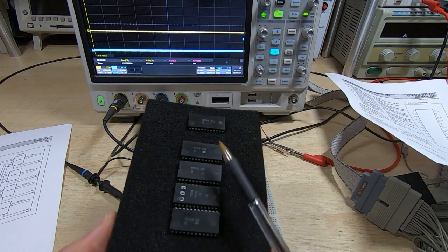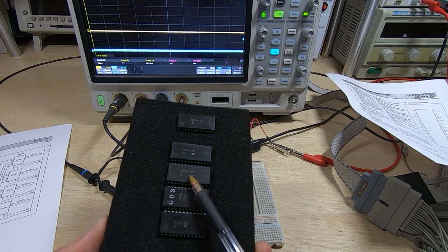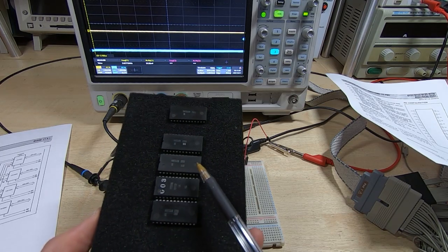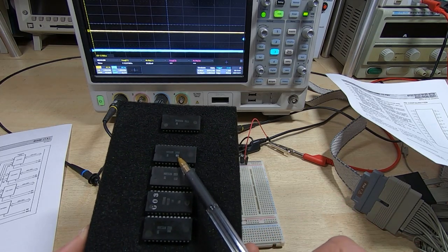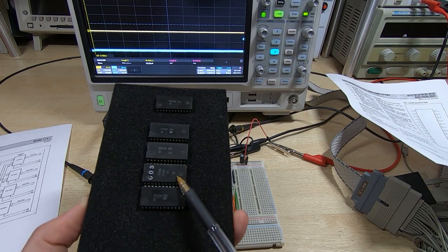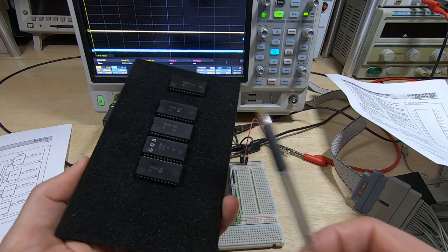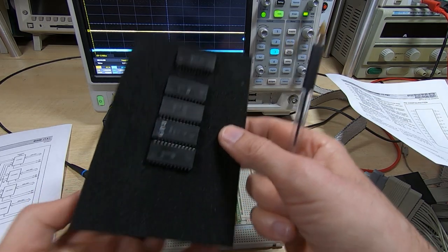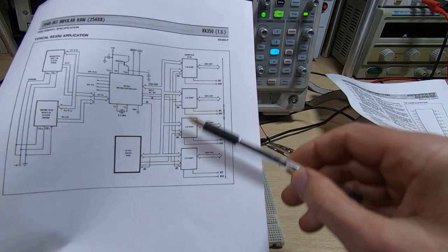Now I don't know if you'll be able to see this or not, but you've got the device here. These are incidentally N8T32Ns. As I said, they're bidirectional latches. So you've got the part number at the top, but also you've got this number down here. This first one says 001, this one says 002, 003, and 004. And this one is much bigger. When you ordered these, you had to specify what address you wanted. And what this does, it enables the system to differentiate between different devices.